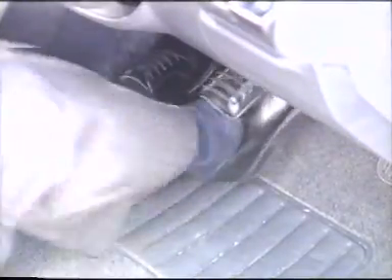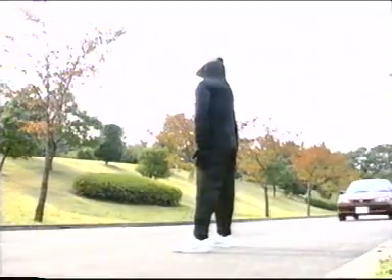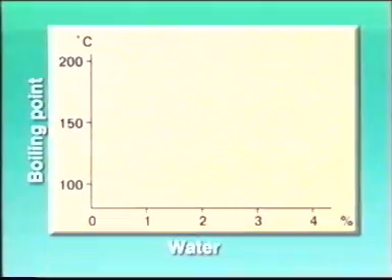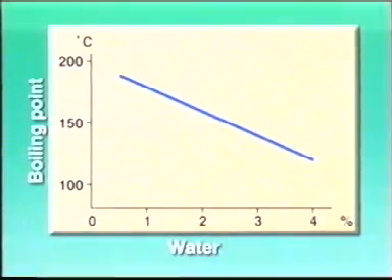If bubbles are generated in this fluid, the pressure will not be transmitted accurately, causing serious conditions such as decreasing the brake efficiency. Vapor lock has occurred. This is a condition where heat, generated by excessive use of the brake fluid, has caused the fluid to exceed its boiling point. It has been found that brake fluid used for a long time tends to absorb moisture and could cause the boiling point to drop.